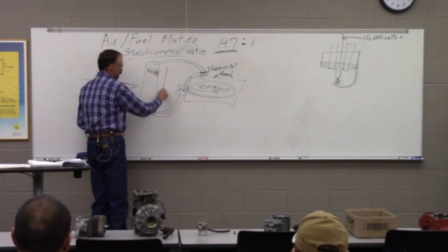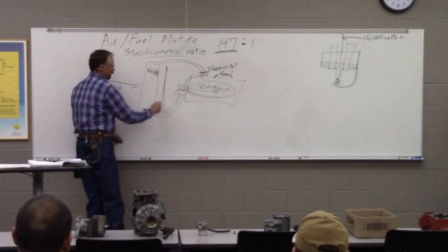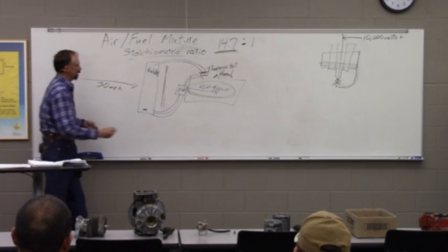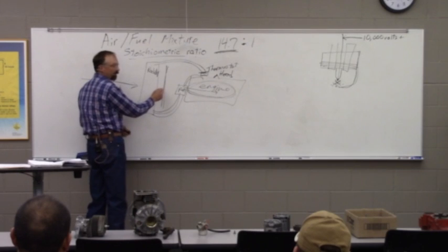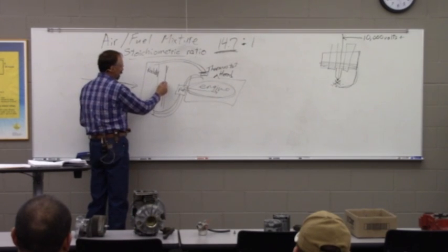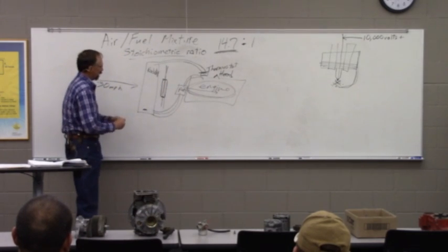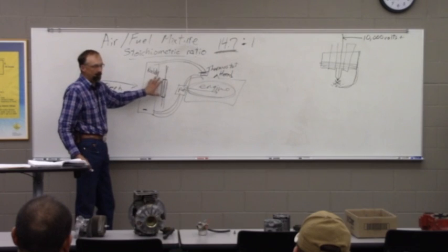So most vehicles will have a fan. Some of them will have a thermal clutch or an electric clutch, or some of them simply are run off an electric motor. But everything made in the last 30 plus years, there'll be a fan there, but there'll be some means of turning it on and off.